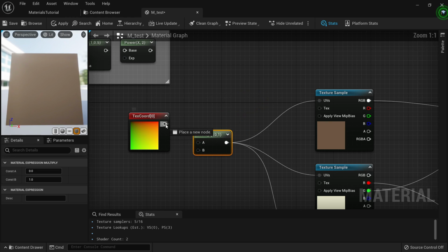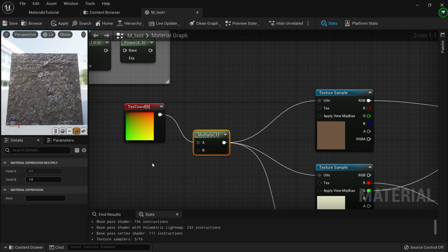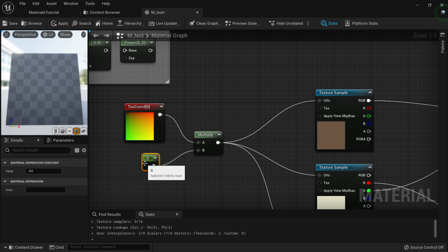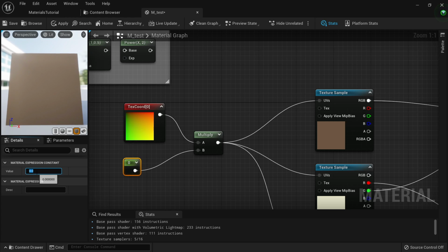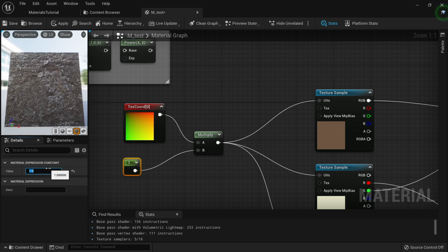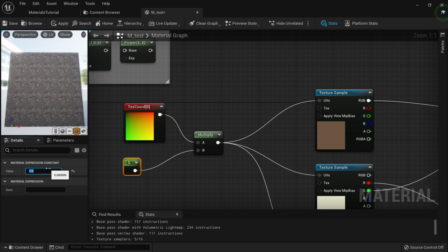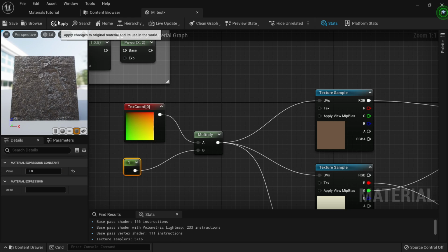Okay, so I can drag my texture coordinates, and by default it's 1, but I can press 1 here and drag this one, and then right click, or let's not convert the parameter yet, let's just see. 0, of course, there is no tiling. 1 is the original one, 2 multiplied by 2, 4, and 5. You can continue to do that. Okay,